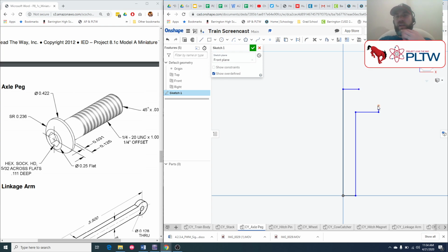Then I've got an arc that connects those two. Two different ways to do that. I could do a center point arc. I have a center point arc, so I'm going to do that one. I'm going to click on this line, click there, and eventually that's going to need to connect up with there. I'm just going to leave it dangling in space right now. I could coincident them. I think that might be an I, yeah. So I is the coincident. If I coincident them, then I've got basically the general shape.